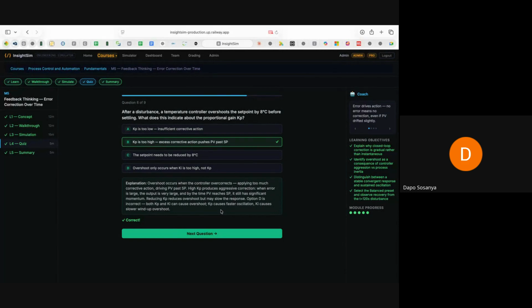So you come in as a control system engineer, you look at all of this, your equipment. Probably they even changed some transmitter along the line, and the transmitter they changed is not like for like. So you tune the process again, taking into consideration the condition of your control valve and your pipelines. Maybe you have some material buildup within the pipeline.